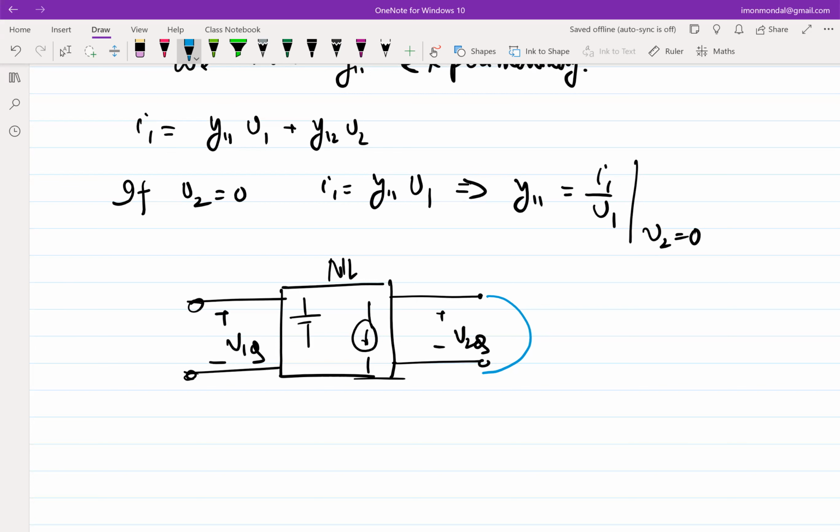I am disturbing the quiescent voltage at port 2. Right? The moment I disturb the quiescent voltage, all my incremental parameters are junk. Incremental parameters are strong functions of quiescent operating points. So you cannot simply short it, even though it looks like from the maths V2 equal to 0. Shorting V2 is only one particular case of incremental V2 equal to 0.